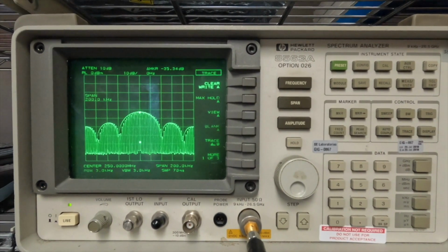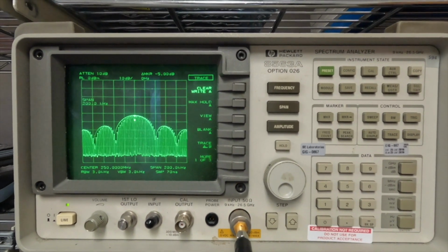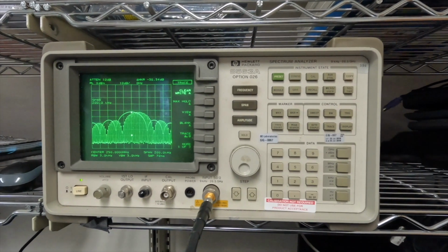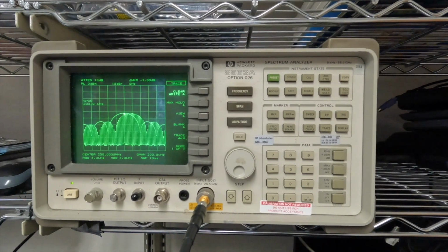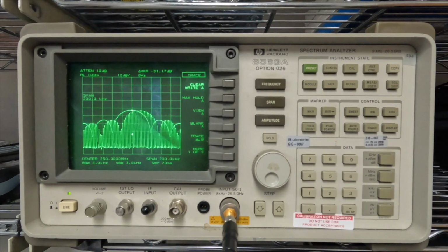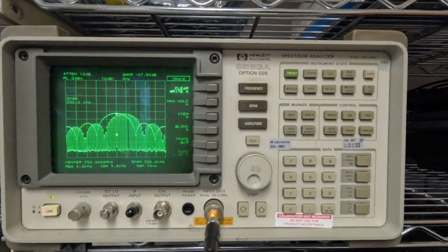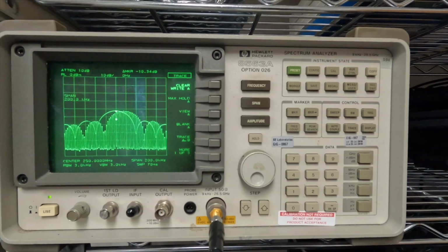So we're going to shift it even more. Now if you look at where it's shifted, it's a higher frequency because we have an inbound target. An inbound target moving into the victim radar is going to look like a higher frequency because of the positive Doppler shift of the targets moving closer together relatively.